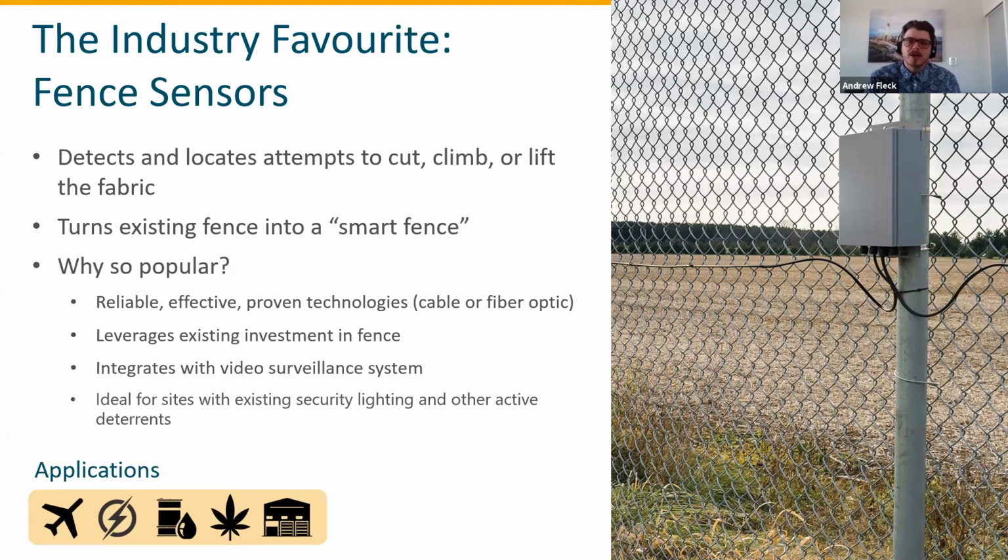And we all know that one of the biggest deterrents to fence sensors has been false alarms. Guards shut them off. Well, if we know that we have a continuous alarm at 152, maybe that guard on their foot patrol can have a walk and see maybe a bag blew into the fence. So these are some of the reasons why me personally, I tend to see that copper fence sensors are one of the more attractive. As well, the price of them has come to a point where they're actually becoming a consumable product. And then lastly, the last thing to consider with a fence sensor, and especially a copper fence sensor, why I lean to them, is the ease of repairability.